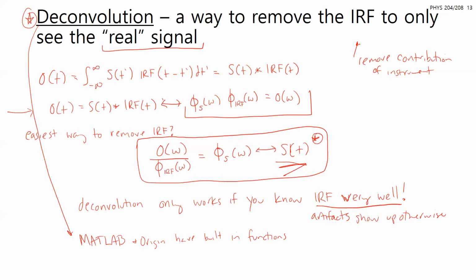I would think that maybe some commercial instruments, very fancy instruments, could do that within their black box type setup. But it's typically a software process. You're not going to do that in a hardware way with circuitry, since that circuitry itself will also have its own response function as well. So it's usually a post-processing of your data.